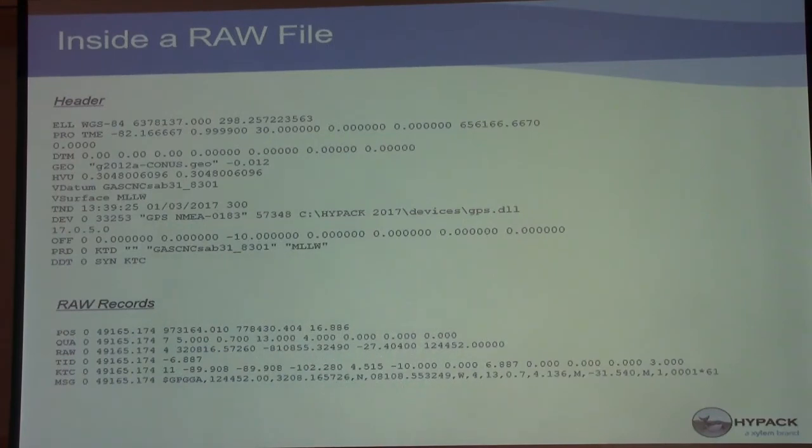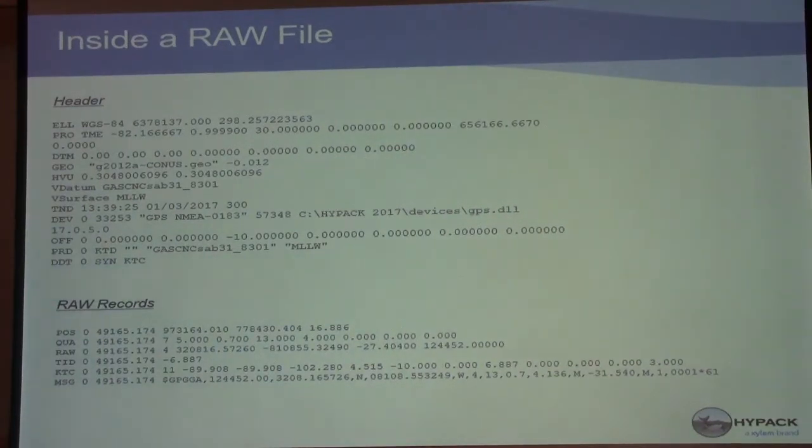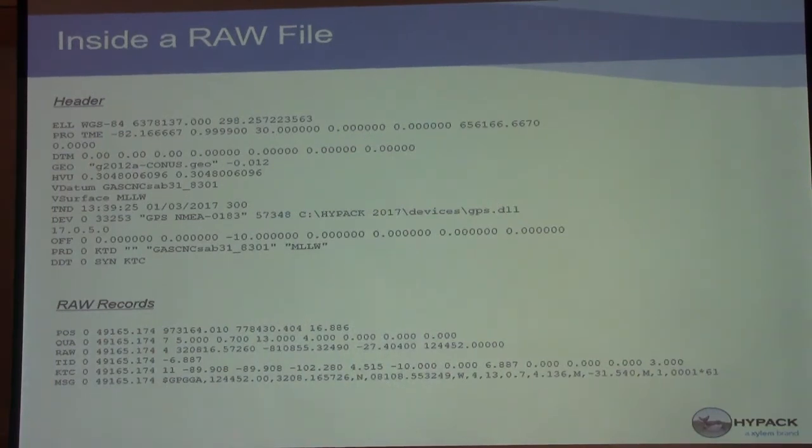And I probably have a description on another page here, but basically all the values that are being used in order to calculate the RTK tides, the RTK water levels. And an MSG, it'll actually write that raw, for example, the NMEA string coming from the GPS. With a POS MV, we write the groups that come out of a POS MV. They're binary, but we convert those over to an ASCII format, so it's a good way of troubleshooting the information.